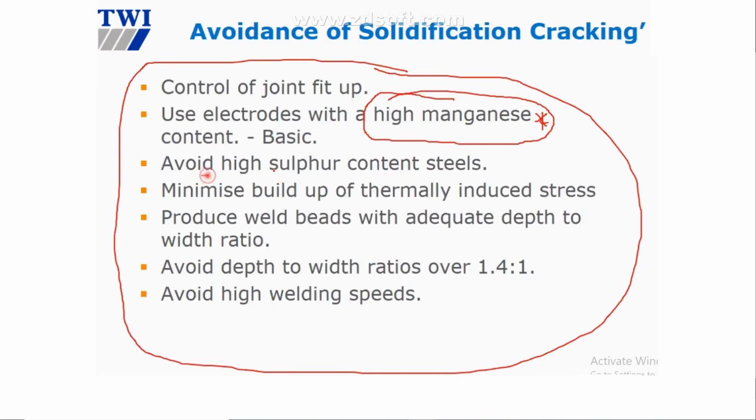Avoid high sulfur, reduce sulfur, minimize thermal stress, right? Produce a bead with adequate depth to width ratio. This is related to the statement here, depth to width ratio. That's the thing you need to memorize a bit in order to avoid solidification cracking, yeah? All right, we move to the next slide.